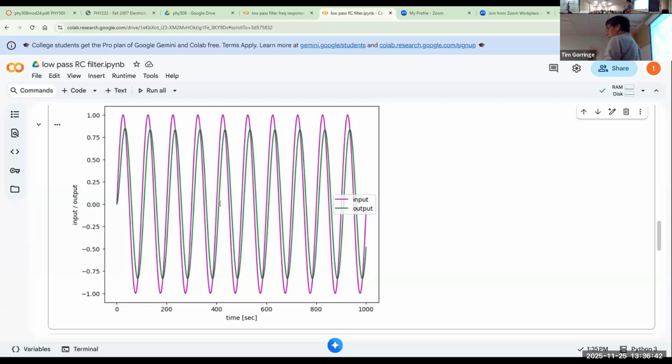And again, this is all occurring because of that feedback that's in a low-pass filter algorithm that is feeding back some of the previous output into the current input and produces this lag. So we're seeing the lag and the feedback in gain now being, maybe the gain is 80%, 0.8 something, and now the phase change is significant, maybe some 10 degrees or something like that.